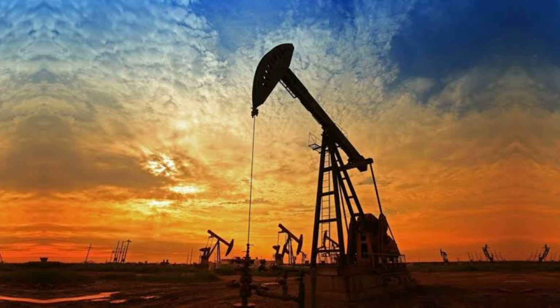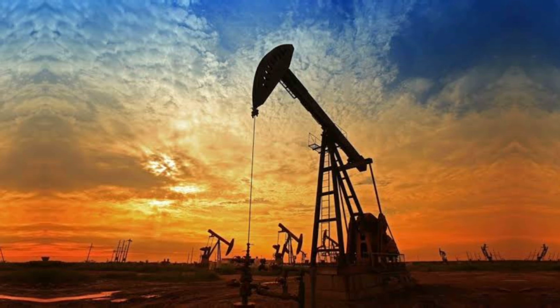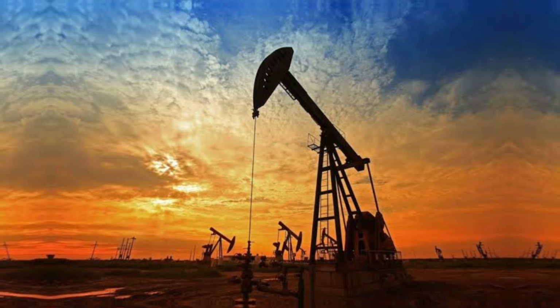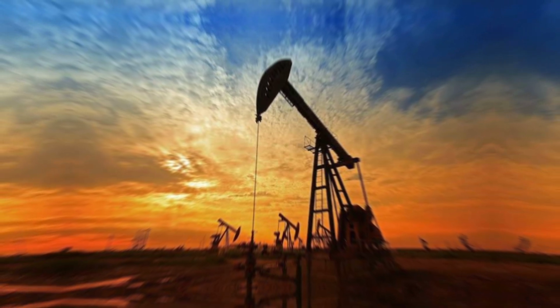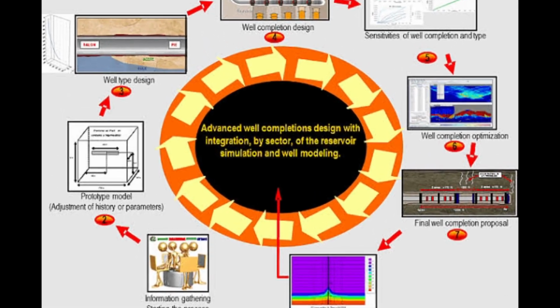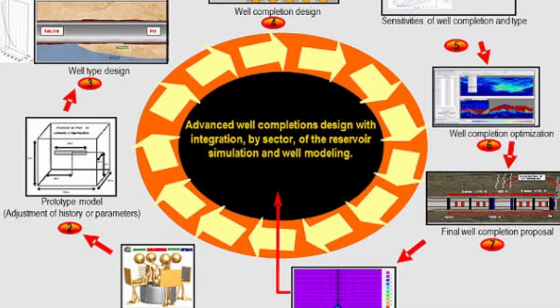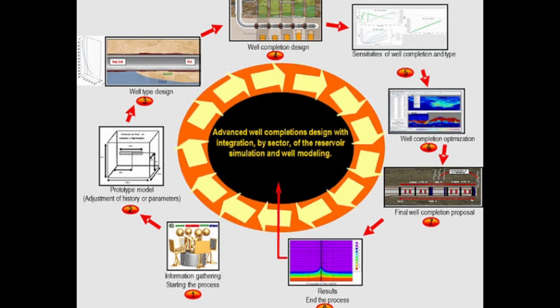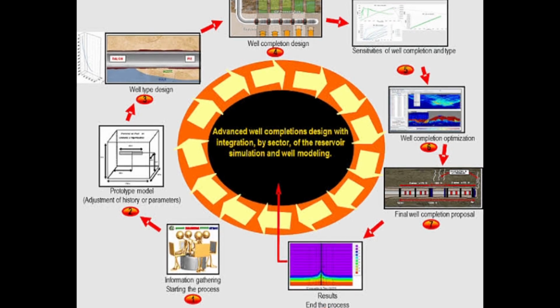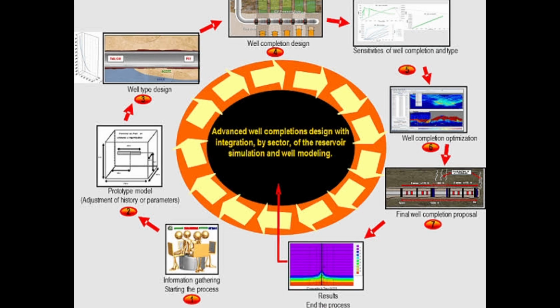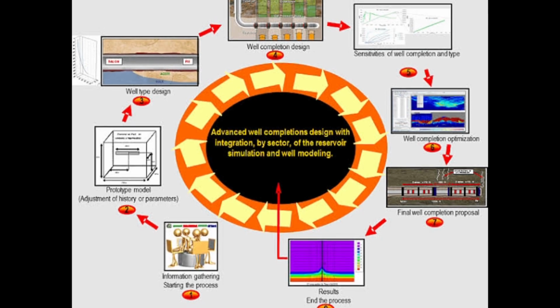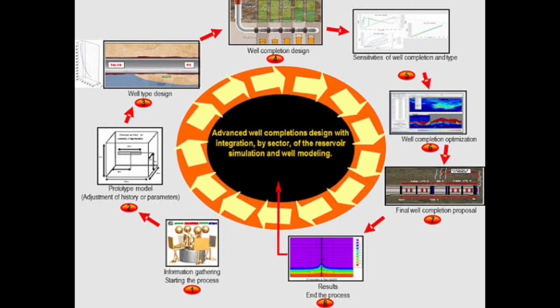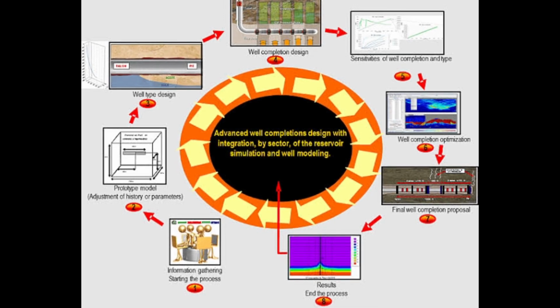By using real-time data like pressure, temperature, and flow rate, and all the other data which we have collected at the time of exploration, we can create a virtual model of the well. This helps us predict how the well will behave under different conditions. For example, by understanding the inflow performance relationship, also called IPR, we can see how much oil the reservoir can deliver at different pressures, and with vertical lift performance, we can get insights into how the fluids will move up the wellbore.